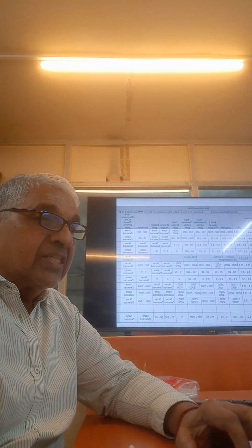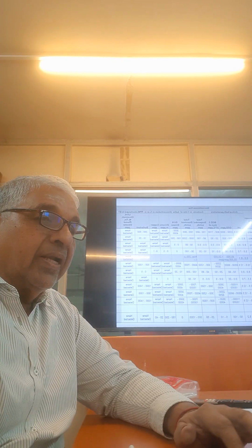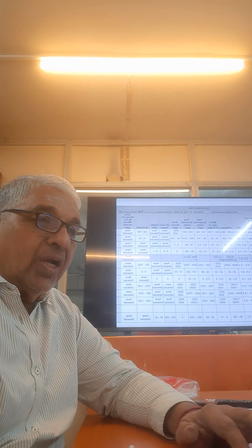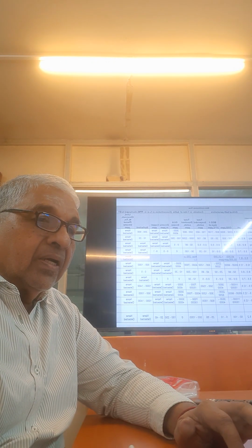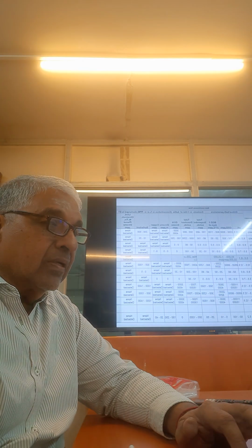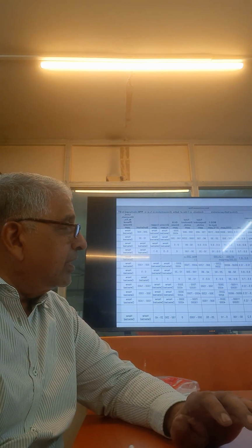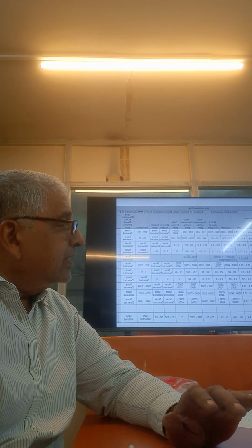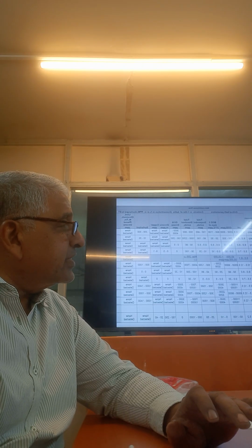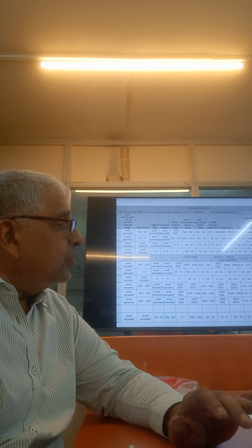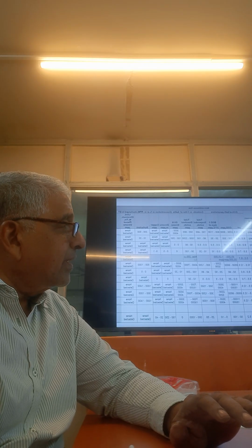But this dump rinse water should not be mixed with the chemical water. Because if the same tank is used for the chemical and the rinse water, then you will have a lot of contamination issues, because you cannot empty the tank fully.